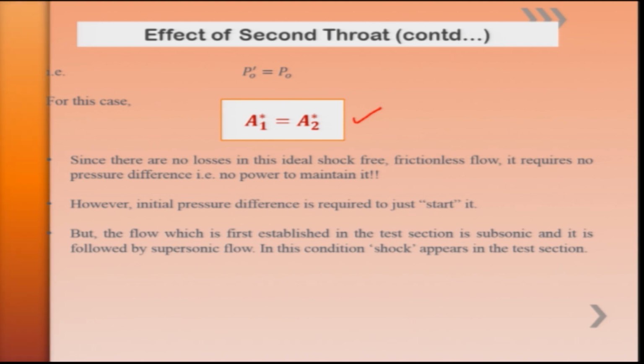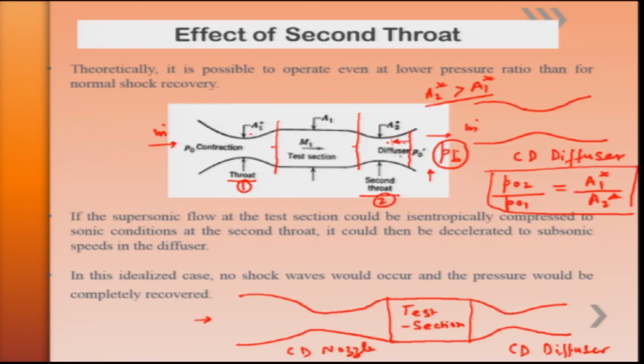A2 star is always more than A1 star, deliberately manufactured or constructed in such a way that the shock does not come directly at the throat but slightly away from the throat on the downstream side. This is because the shock, as soon as it becomes unstable while directly at the throat, can be slightly affected by some perturbation or external causes, and then move or travel further upstream.